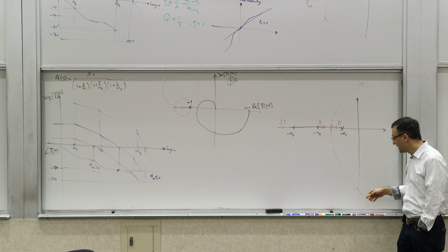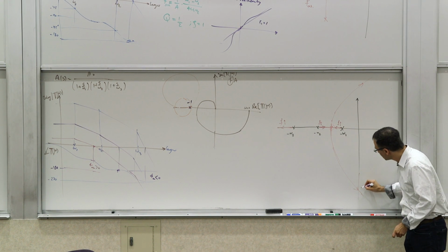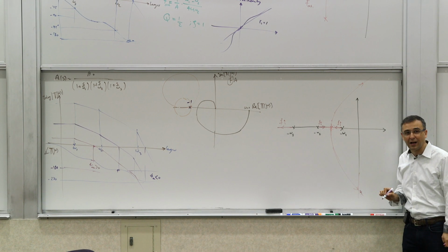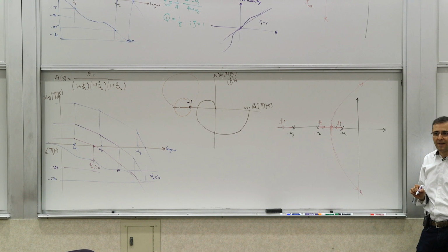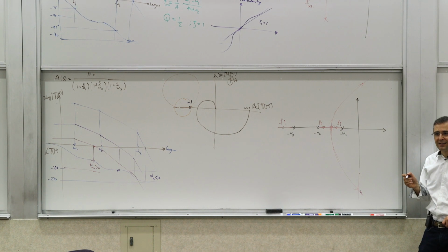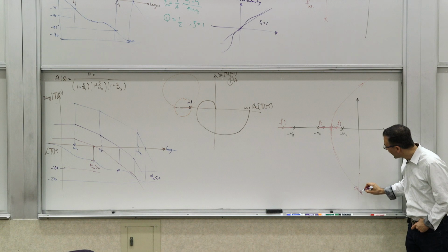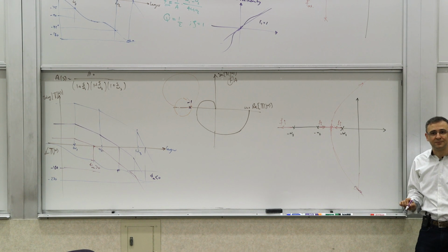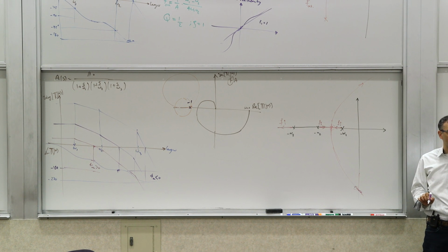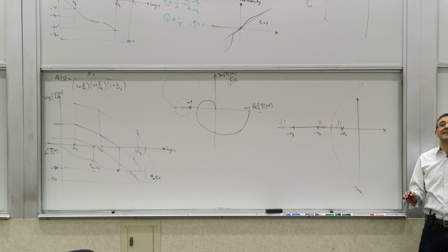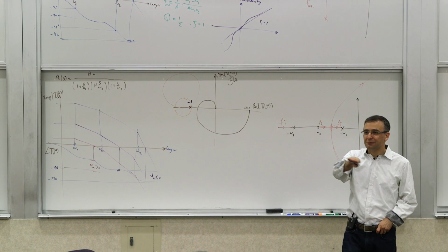So what you would need is a system that, if the poles for some reason go a little bit farther out to the right-hand side, reduces the loop gain and brings them back in. And if they go a little bit to the left-hand side, it increases the loop gain or increases the feedback and brings them back. So it's a stabilization of an unstable system.